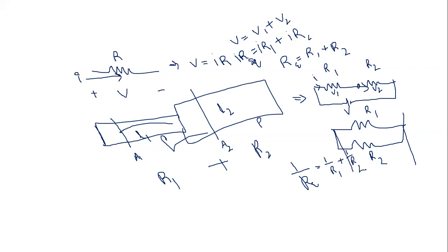In such a manner, you can take any type of connections. Maybe you can take star connection or delta connection or a combination of series and parallel connections. Using simple series and parallel combination reduction, you are going to find the final value of the current. Of course, you can take any geometrical construction of the resistors, but you can apply the simple Ohm's law and reduce the equivalent resistance of any network consisting of n number of resistors. Like that, you can identify the equivalent resistance, right?